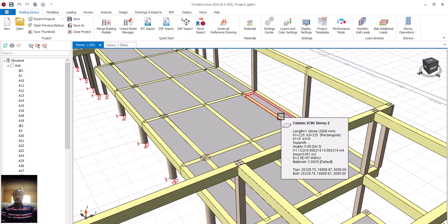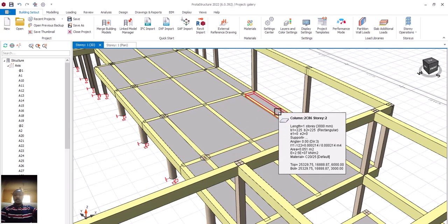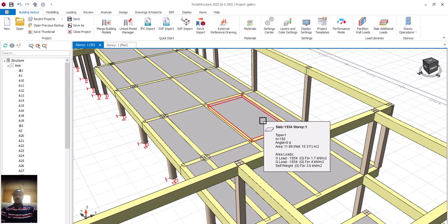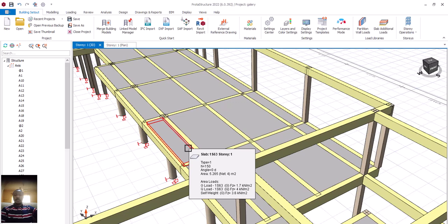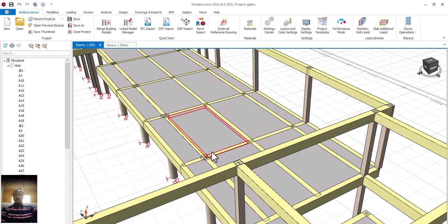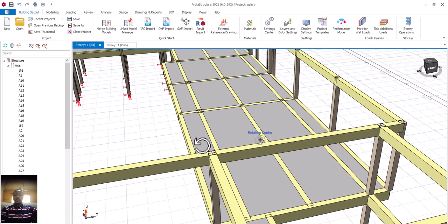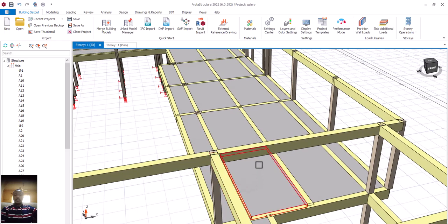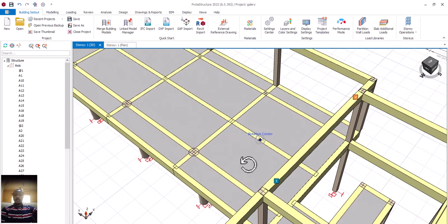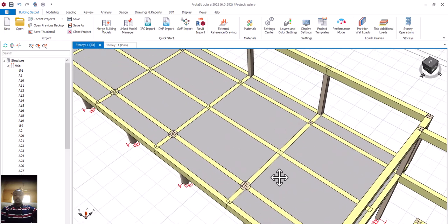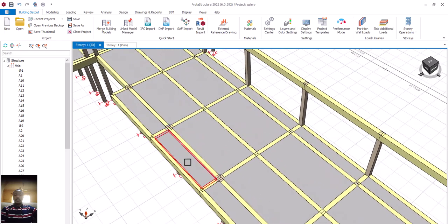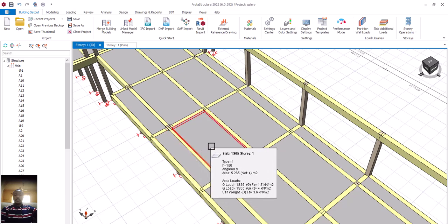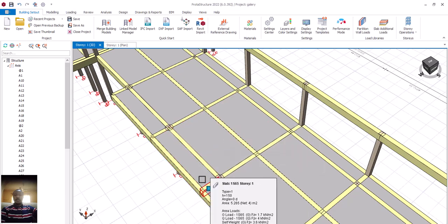So that is that. This place is normal, and based on the architectural drawing, from this place you step down to this place by 225. Understand? And when you are coming here, you also step down by 225, and this place is going to be 150. Now why is it doing that? It is because it does not want a situation whereby when people are entering, they leave space in between here. No, you want a situation whereby as people are coming here, they follow here and enter like this. You go like this, you enter like this, and also you go like this, you enter like this, etc. So that there will be space. The arrangement will be such that there is a small space in between. Okay, so as you're coming like this, you enter like this.